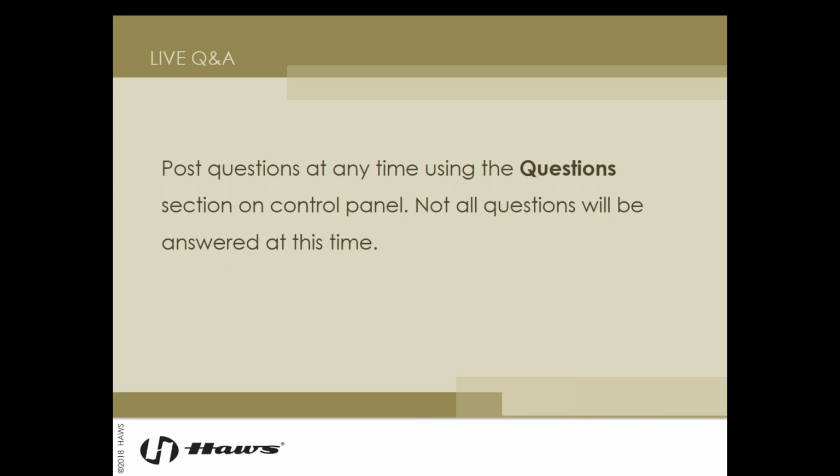Guillermo was wondering, for existing facilities not planning to remodel, how many units need to be accessible per floor? Every floor needs to be accessible. Now there may be floors in a building that for some reason don't have elevator access, because the nature of the work that's conducted there is too dangerous for a person in a wheelchair. That happens. There are certain laboratories that can meet that exception. But otherwise, every floor needs to be accessible to and usable by disabled people, just like the able-bodied.